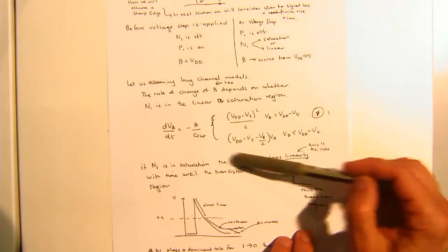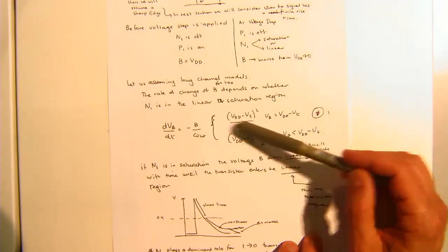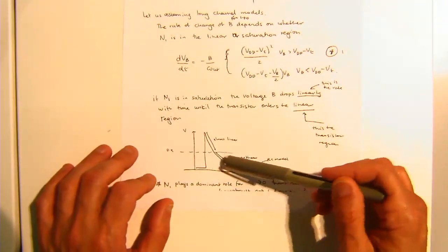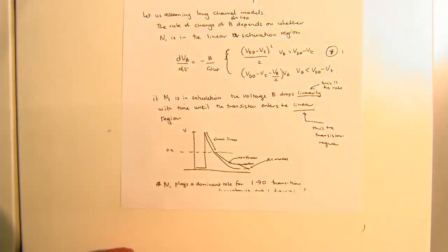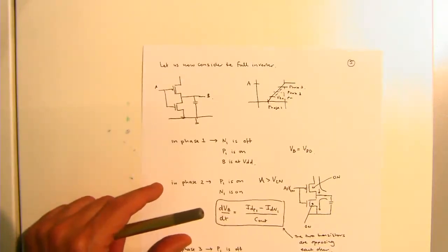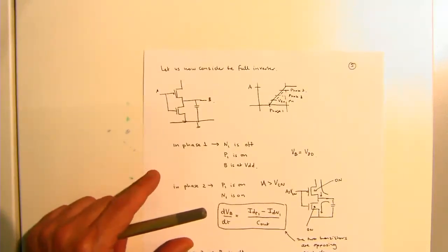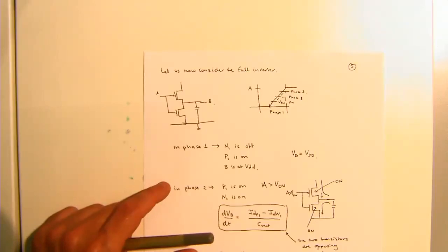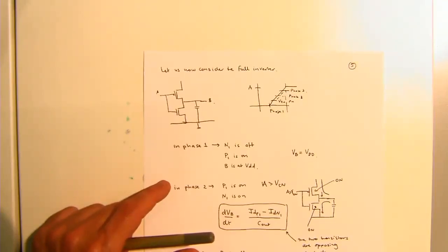And if we're in the linear region, we start getting this non-linear effect where essentially what we're seeing is this exponential type of decay in the signal. Okay. Then what we went on to discuss was, well, we're making an assumption here, and the assumption is that the gate voltage is changing abruptly as a step. What happens when we have finite rise times at the inputs?